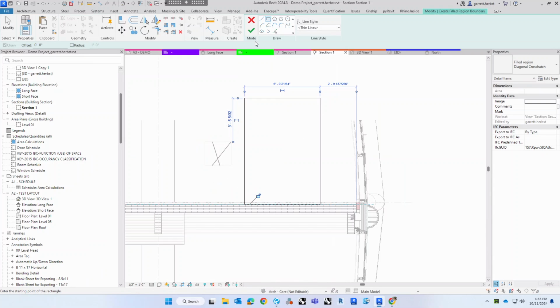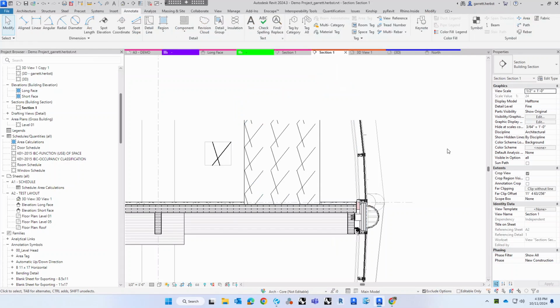Of course, what you would use that for, I don't know, but custom metal panels, very unique custom layouts, tiles, all that good stuff, like stacked tiles or bricks, right? You can't build that in the native Revit hatch elements. You have to build those from scratch. That's actually how I built the CLT pattern.